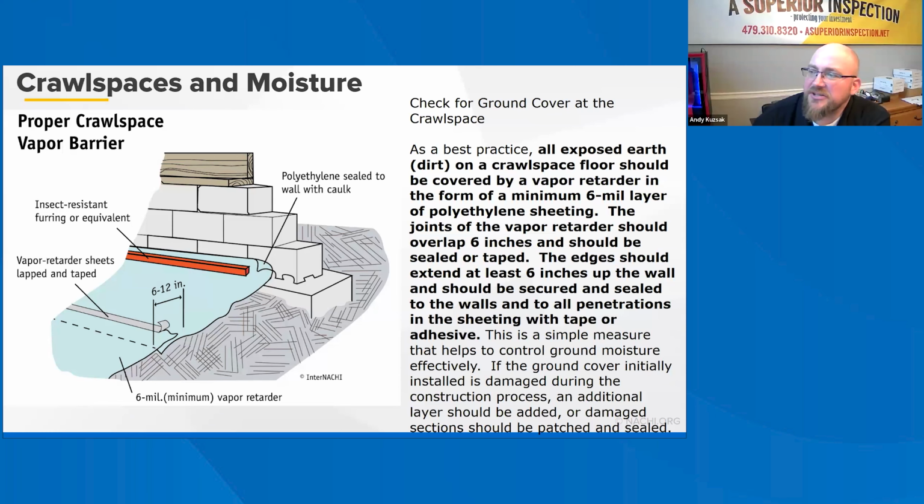If the crawl space elevation is below the exterior finish grade, foundation drainage and damp proofing, such as a bituminous coating, should be provided as required for basements. Crawl spaces should use these measures along with exterior drainage systems. There are 2 choices for crawl space ventilation: